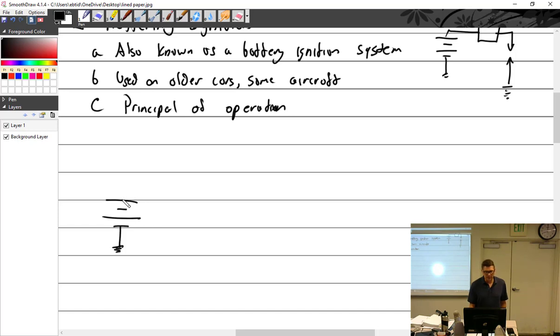All right, so we can't have a battery, but where I was going with that is, guess what we have now? When I just replaced the magnetos on my airplane, because you want to do a 500-hour inspection on a Bendix every 500 hours, and if you have a Slick, you really should throw them away every 500 hours. Given that I was taking my airplane across the country twice, I thought, I don't need a magneto problem in Kansas somewhere. So I hit 500 hours and put on some brand new overhauled ones.